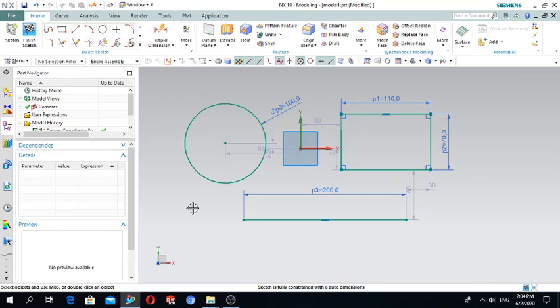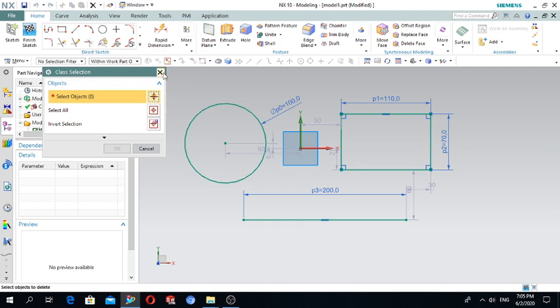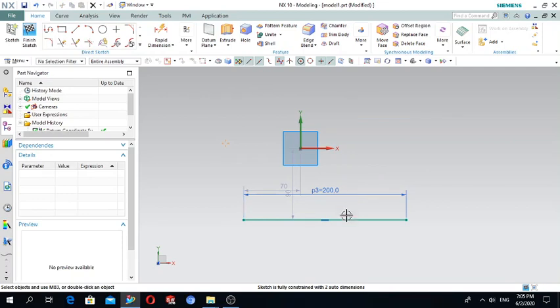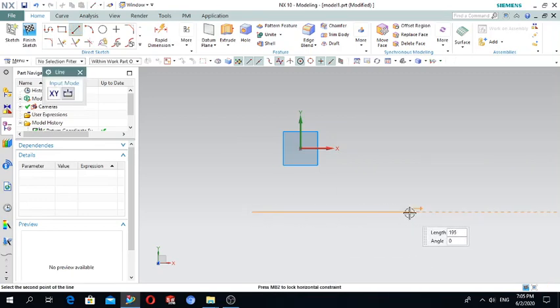There are also several other methods to put dimensions, for example, linear dimensions, angular dimensions, and vertical dimensions for lines. Let's first delete this sketch. Select all. For example, linear dimensions. NX allows you to create various types of linear dimension. Firstly draw a horizontal line.